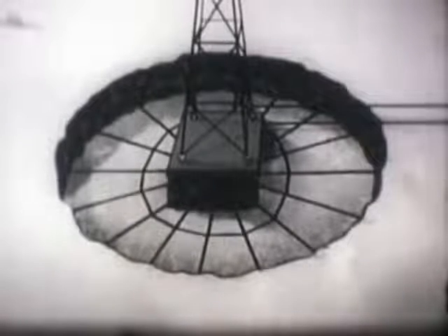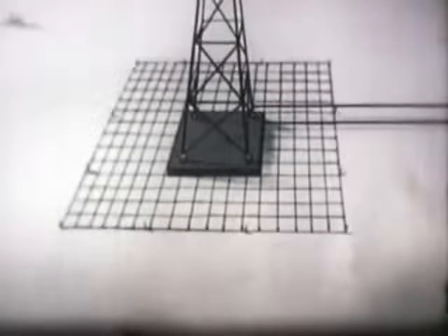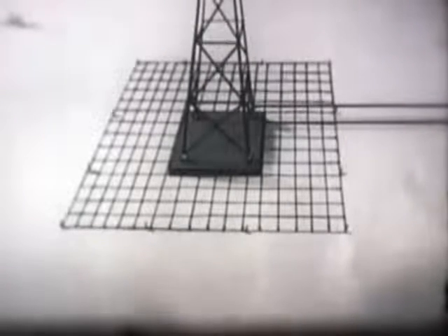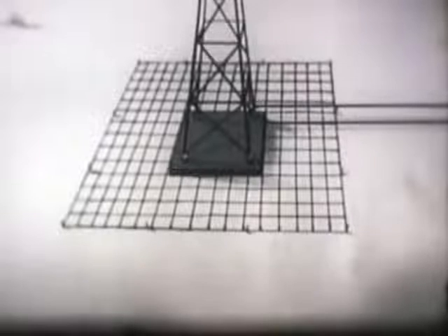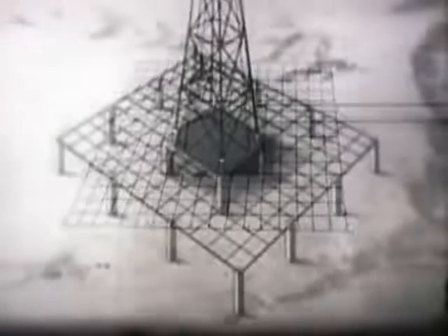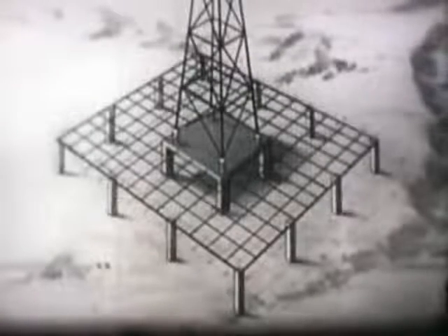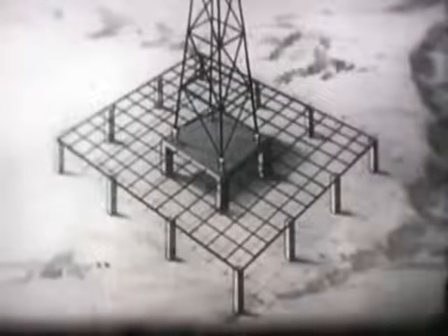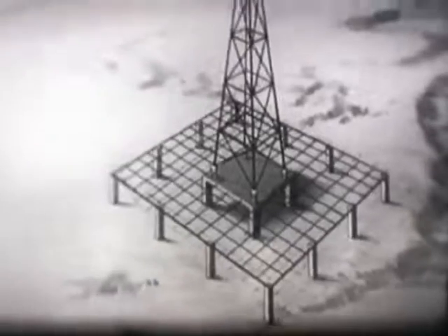These radial conductors are connected to a common point at the base of the tower. Sometimes on some installations, an additional system of wires lying on the ground, called a ground screen, is used, thus forming a more effective ground. Where it is not practical to bury conductors, a network of wires called a counterpoise is built above and insulated from the ground.